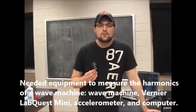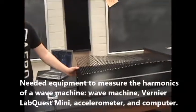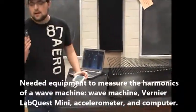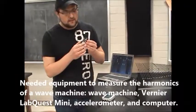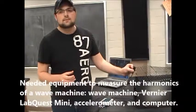Today I'm going to explain how to measure the harmonic frequencies on a torsional wave machine. For this experiment you need the torsional wave machine, a LabQuest Mini interface, an accelerometer, and a small piece of plexiglass to be able to tie the accelerometer to the wave machine.